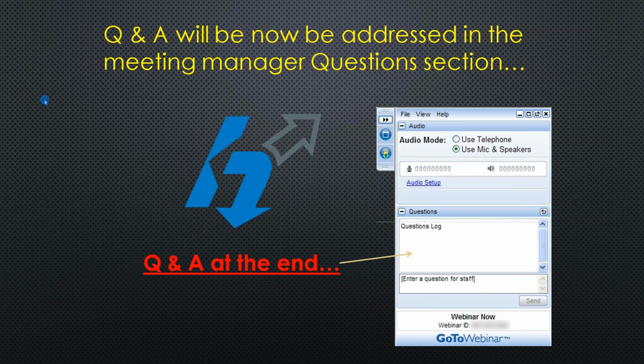There are actually sub-tests happening inside that in the background. You don't actively see it. You see it with the nonlinear analysis, you see those tests run. But on something like a linear analysis, it's hidden. The convergence in there is giving you results based on those internal tests converging. You still need to run mesh refinements and run separate tests manually and plot out and chart those results.